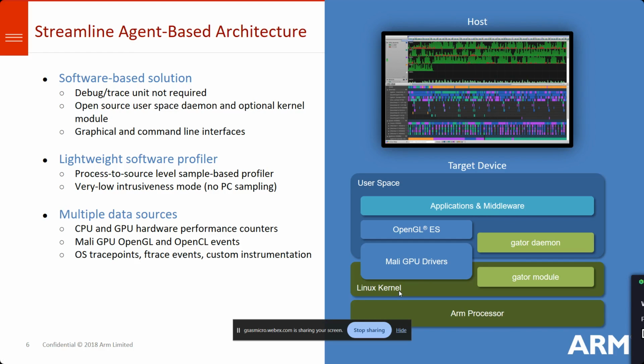You may be thinking, Madam, Cortex-A might have so many counters, probably 10 to 20. So Streamline will still sample all these counters? No. When you are initializing the Streamline Analyzer, we have to specify which specific counters you want to see the performance of. Like I want to see only cache hit and cache refill. I don't want to see cache miss. Then whatever counters I added, only those will be sampled and it will give you the information. So that is how the gator daemon works.